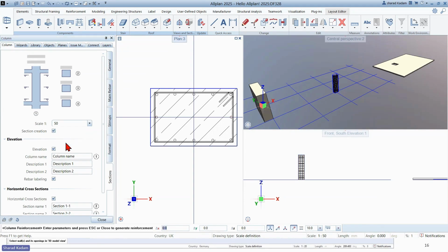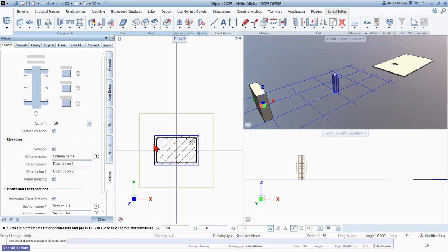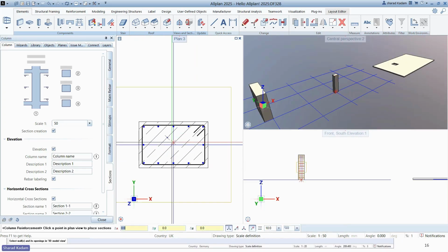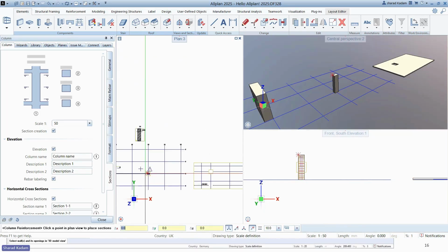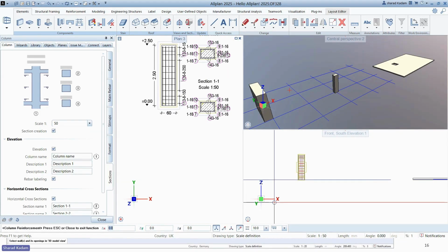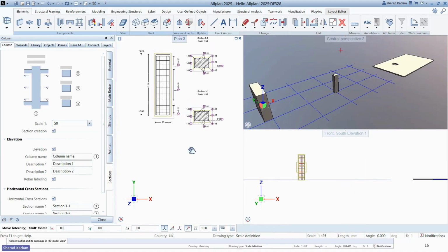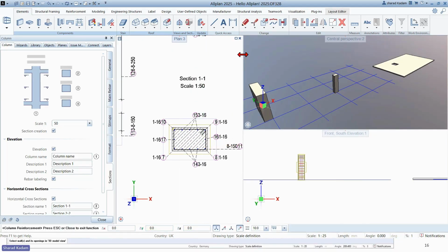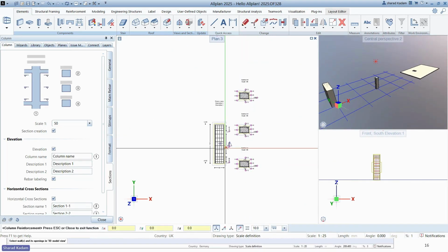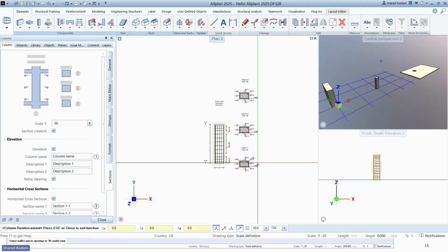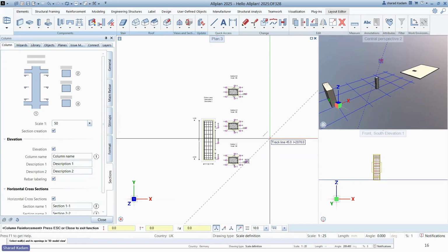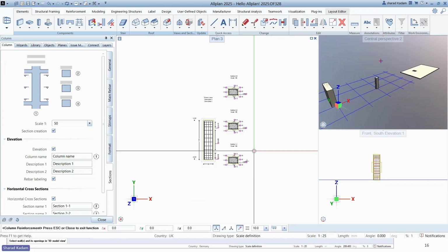That means if I just click on this button and close this, it has identified it, it has put the rebars to it. We can see that in this particular location, and I'm just placing my column sections out here. It has also given me the tagging as well. If I just change my scale, all this tagging has been done at the same locations. Like this, we can use this Python parts to add rebars. For main bar, stirrups, and side by side, we are getting the cross section done as well. This is a really good tool not only for modeling but drawing generation as well.